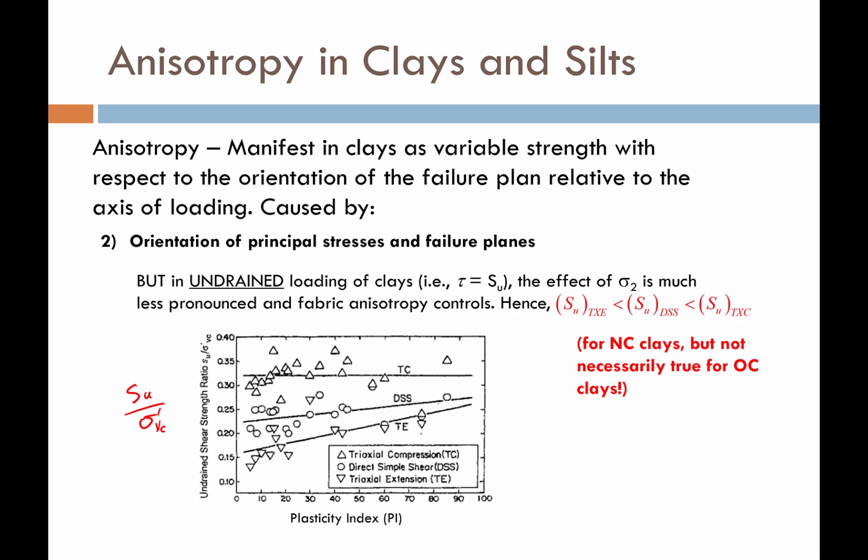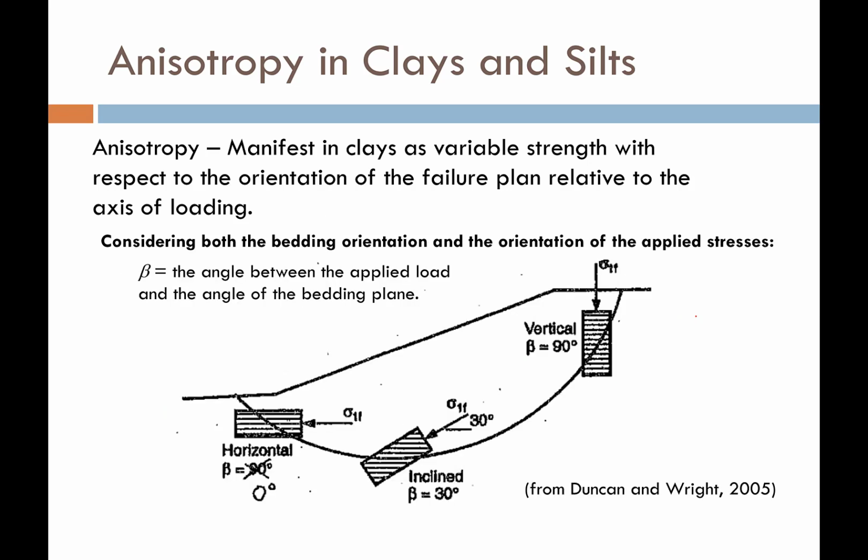Now, it's important to note that this figure and this relationship is true for normally consolidated clays, but it's not necessarily true for over-consolidated clays. Well, why? I'll show you in 1 minute. But first, to show you this figure, let's get a little bit of vernacular down. And let's look at just a schematic of a failure plane in a slope. Now, you can see that the soil is deposited in horizontal layers.